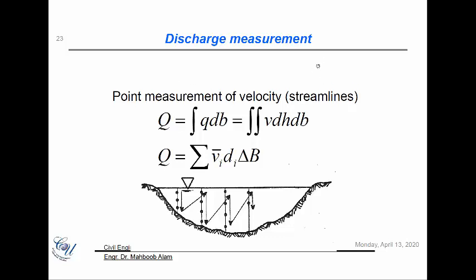What we basically do is that we compute velocity throughout the width of a certain stream flow, and then we are computing velocities at different depths. So we would reach a certain point, and we lower our tool that we are using for velocity, for example the current meter, which is one tool for measuring the velocity. We'll lower that tool to a certain depth.